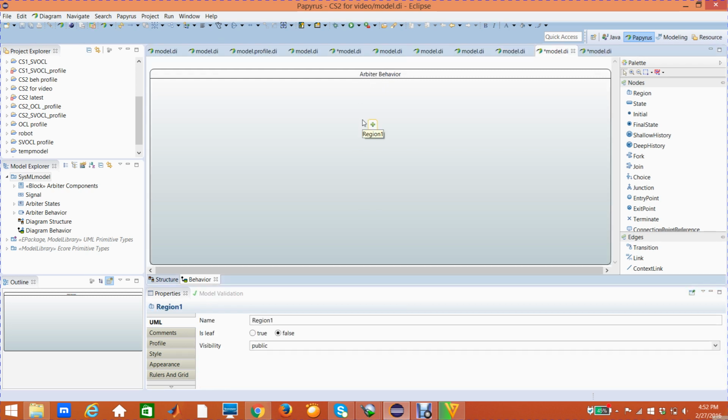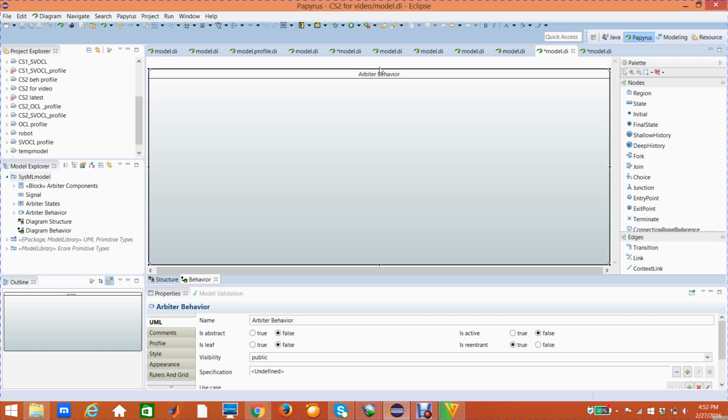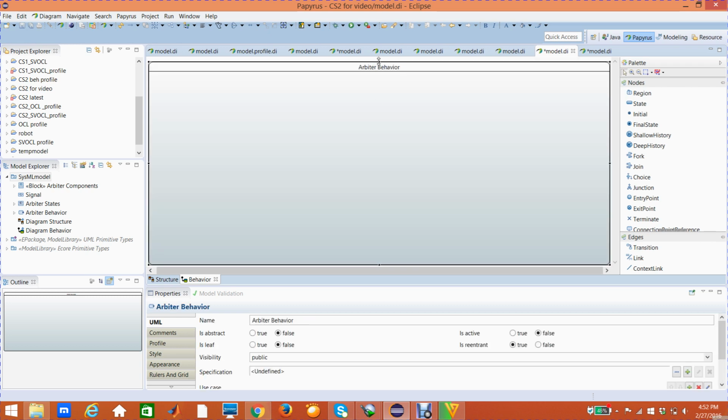To model the behavior, first of all we will take the states of the Arbiter case study. We said in the last video, in the structural aspects video, that the Arbiter controller has 7 states: one idle state, 3 master states, and 3 respective masters' idle states.